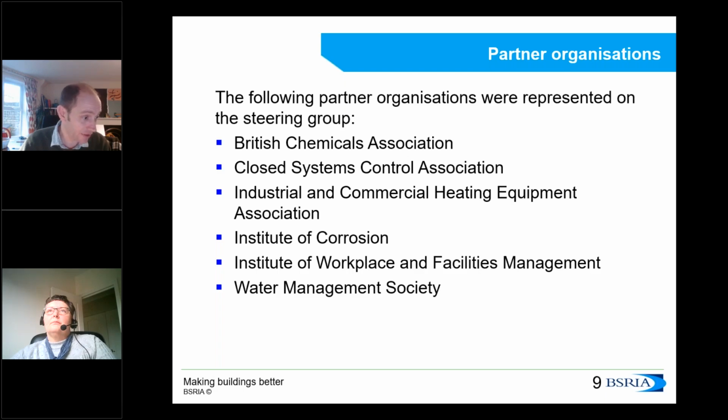Engin, apologies if I have your name wrong. You've talked about plastic pipework there. That's a very interesting one, because plastic pipework doesn't undergo corrosion per se, but it does undergo chemical attack, and certain types of plastic pipework are particularly susceptible with certain water chemistries, and they need to be compatible with any water treatment chemicals that are used.